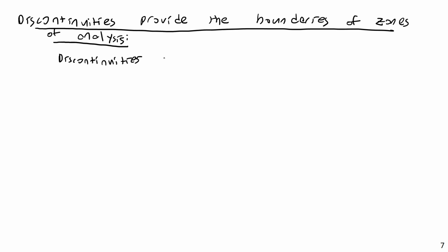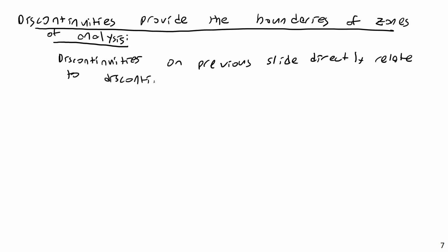So fundamentally, the discontinuities previously discussed, or on the previous slide, directly relate to discontinuities in the V and M functions, in the shear and moment functions. Those are directly and inextricably related.